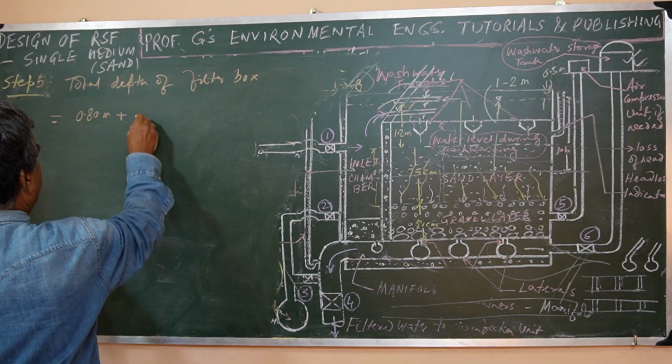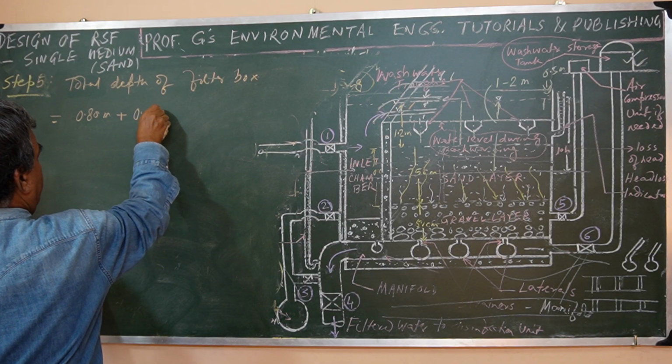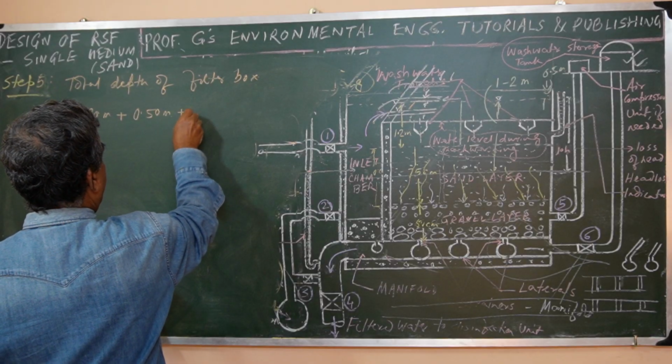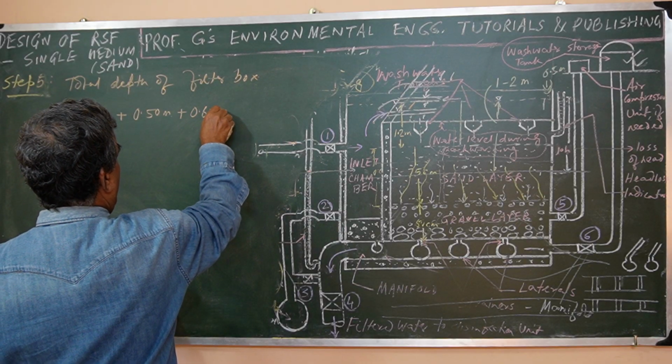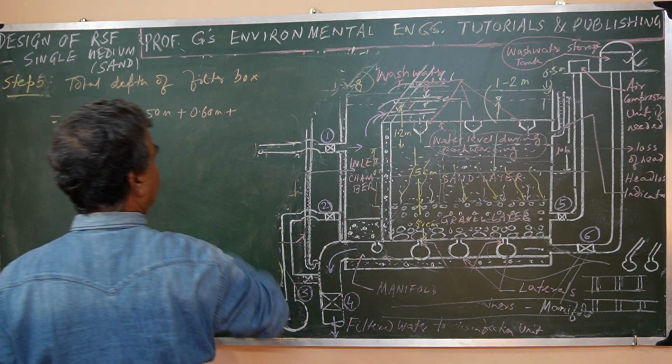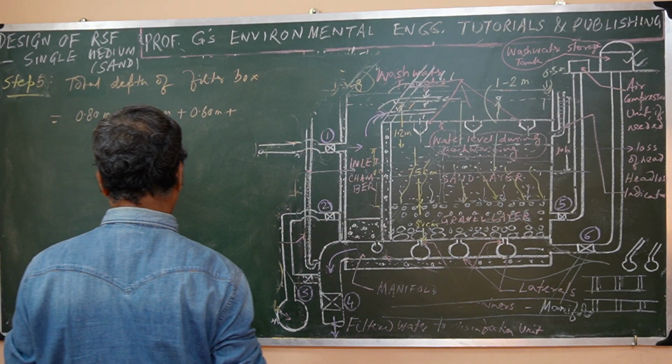The gravel depth is 0.5 meter, sand depth 0.6 minimum we had to provide. It was coming 0.46, but this being minimum, we have provided minimum.